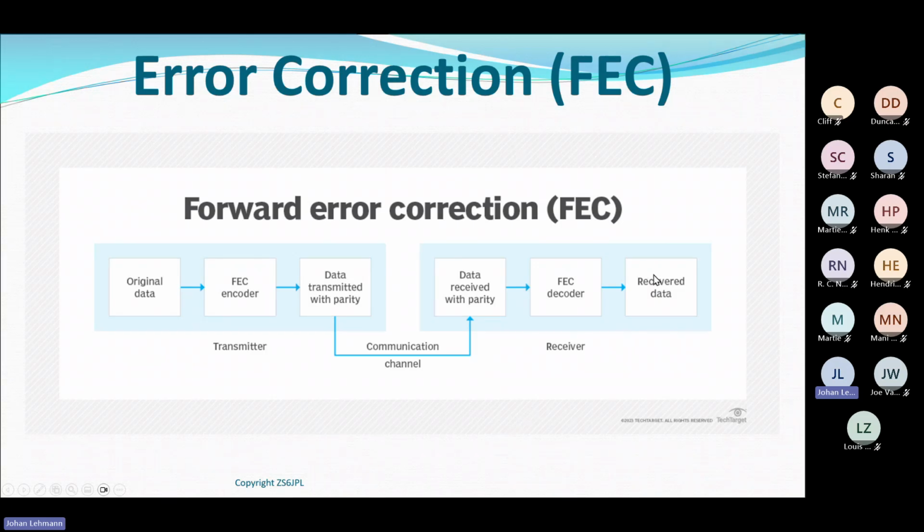So that I can see on my screen, let's say this side we type the words hello friend, on this side of the screen will appear hello friend, because the forward error correction decoder would fix any mistakes within limits that it can. And this can be done now without asking the transmitter, please repeat, please repeat, please repeat. It fixes it automatically on the fly without the transmitter even knowing.